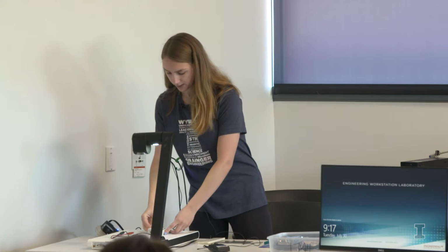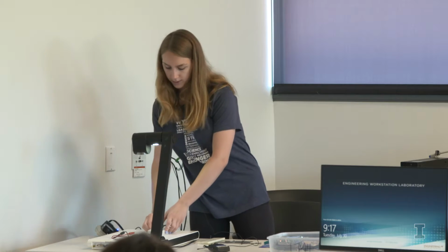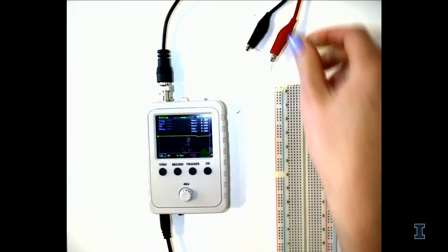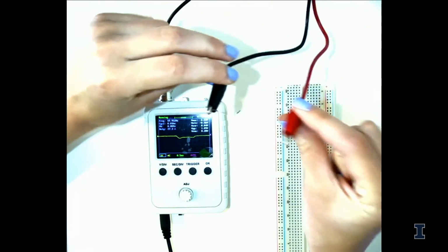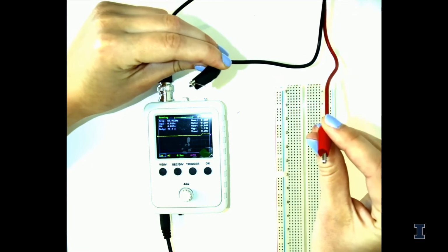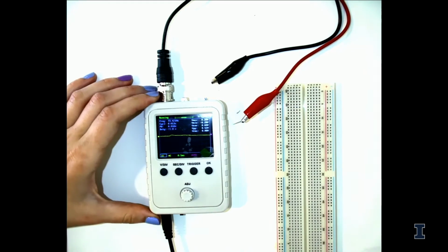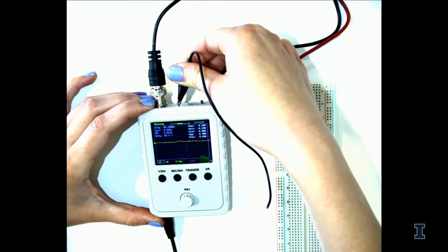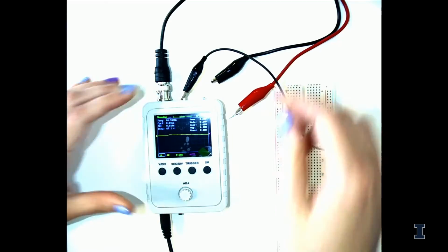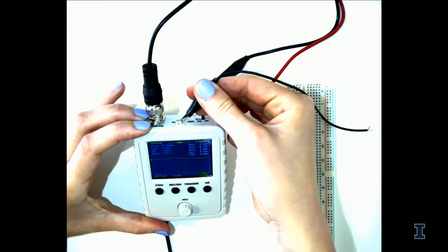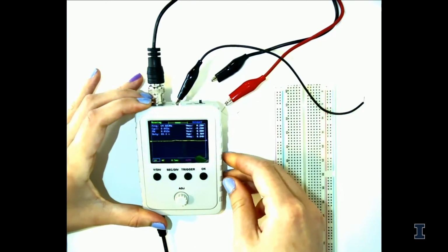So I'm going to turn this on here. If you want to just watch to start, I'll go over the basic controls. Right now, on the projector, you can see that there's just noise because the wires, or the probes, aren't attached to anything right now. Also, on the oscilloscope, this one has a 1 kilohertz signal automatically generated for you. That's the little knob at the top. There's a little metal piece, and that's going to give you a 1 kilohertz signal.